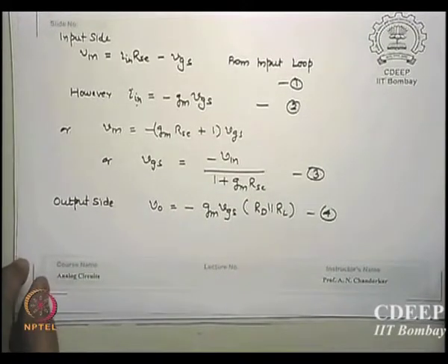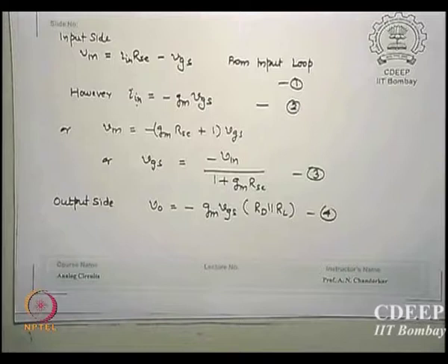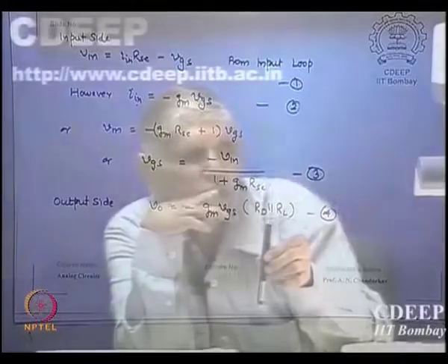Is it okay? What is the phase difference in the case of MOS transistors between drain current and source current? The same. So what should the V0 by Vin gain be, it should be positive, because all of these are going in the same direction downward. Input is at the source, output is at the drain, it should go in the same sense. Let's see whether it comes. Is that clear? Since the drain to source current is in the same direction, if I input at the source and collect the output on the same side, they should be of the same sign. Let's see whether it comes.